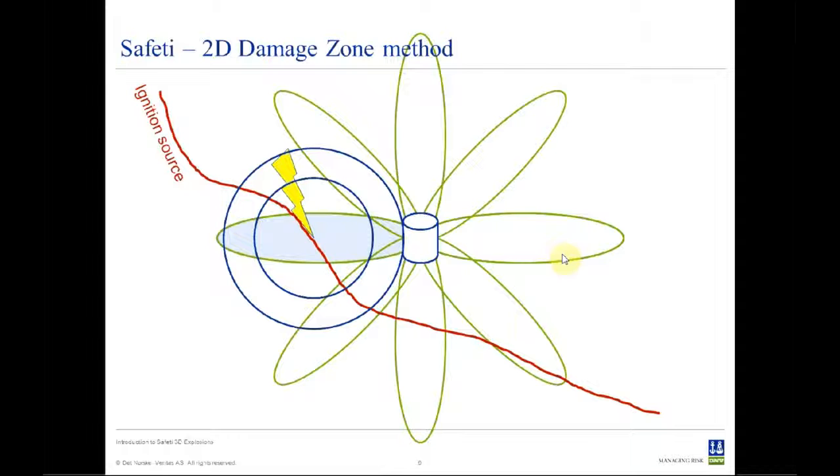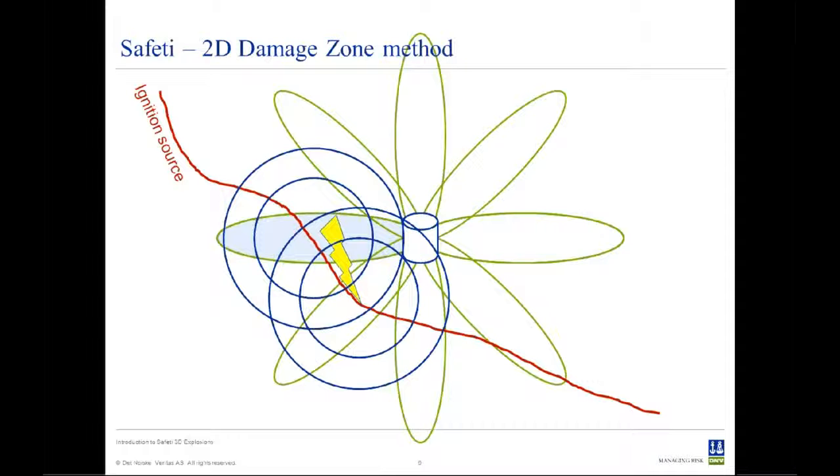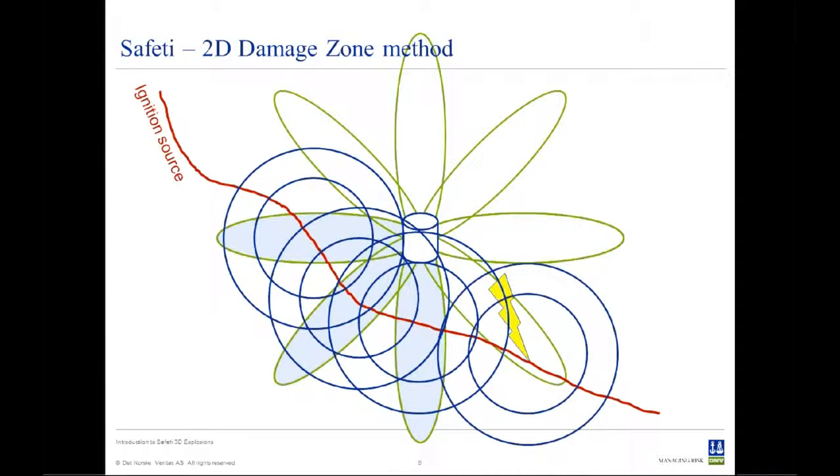which is governed by event trees. Ignition will occur again at other locations where flammable clouds and ignition sources intersect, and we'll get more blast zones and flash fires. And this will keep occurring all the way around the windrose and at different time and distance steps throughout the cloud. Of course, this has been simplified, as busy as the diagram looks.